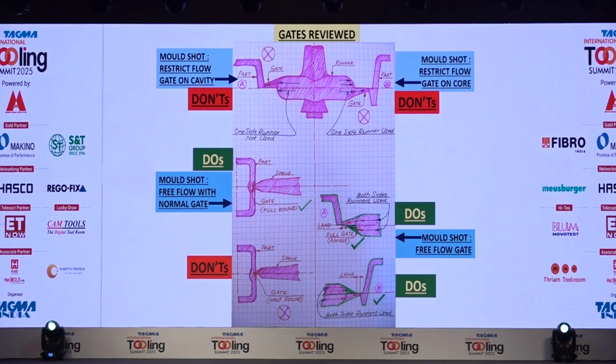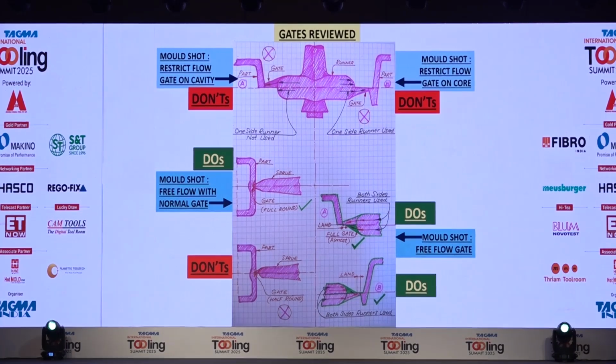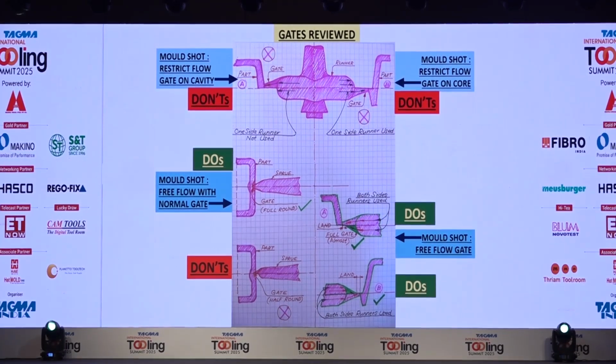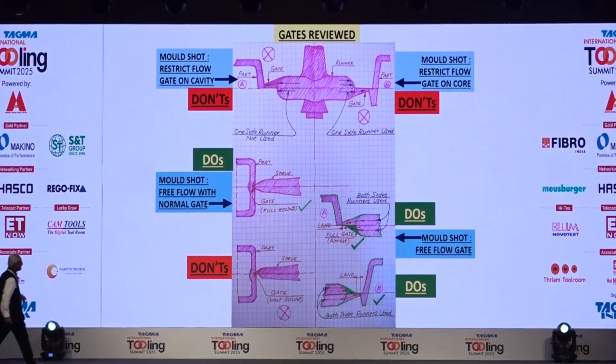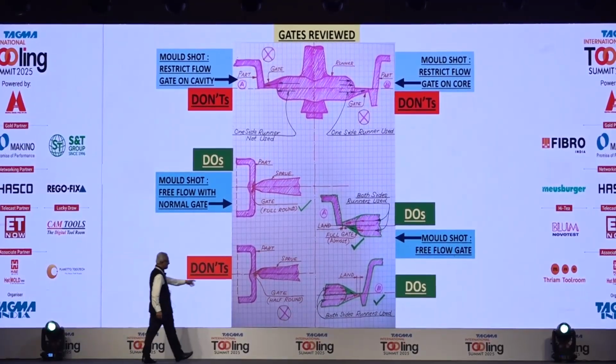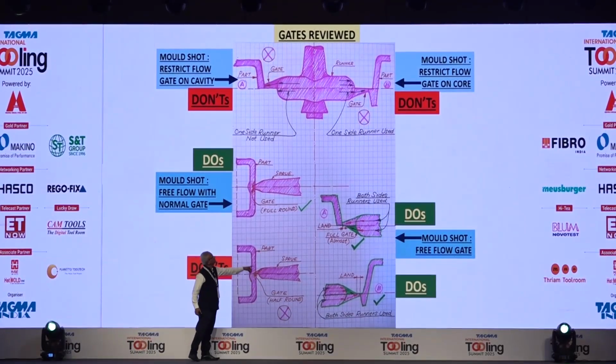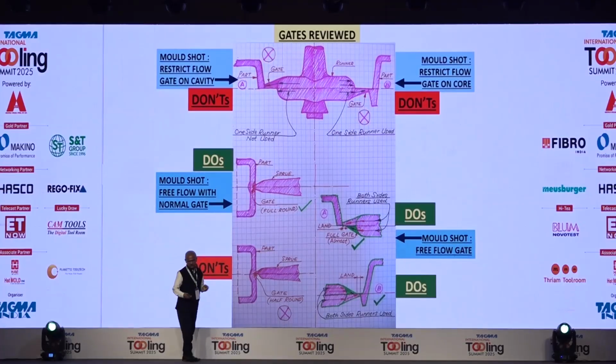Similarly, as another example, on the left bottom you can see a 3-plate mold with a center gate, where the gate is round and we make a round electrode. On similar grounds, on the right side top, if I make the same half round here, we have made half of the gate. It is difficult, that's why this is not made. There it is easy, that's why it is made.